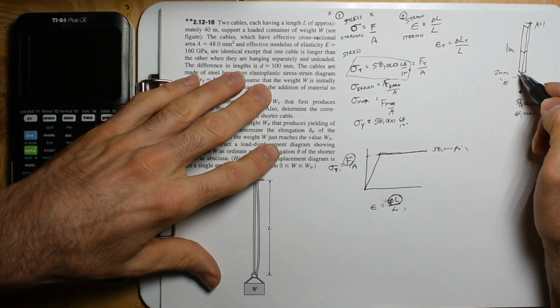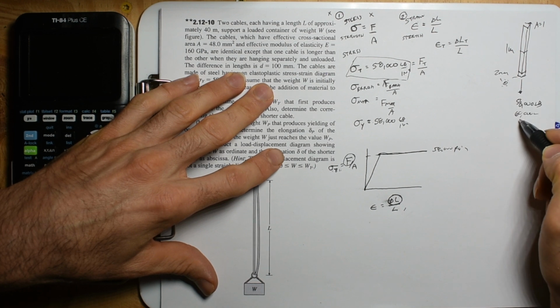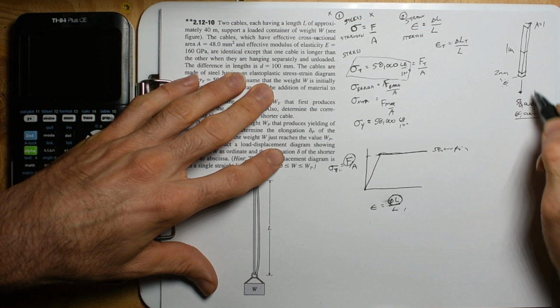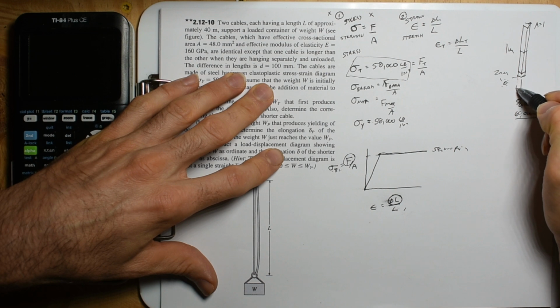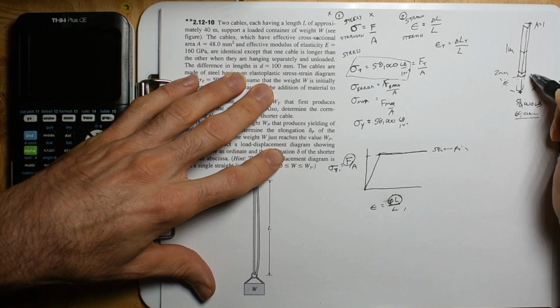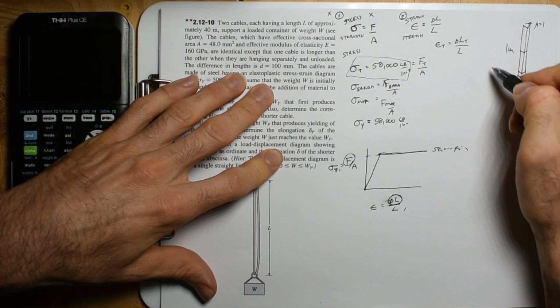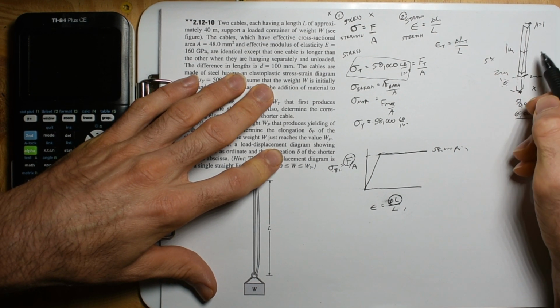The second that you observe this 2 millimeters change in length and then put more force on it, the thing's just going to change in length until it breaks. And if you're not super cautious about the moment it elongated more than 2 millimeters, you have to catch it before it elongates, let's say, 5%.